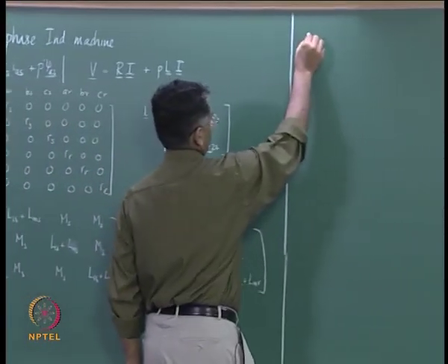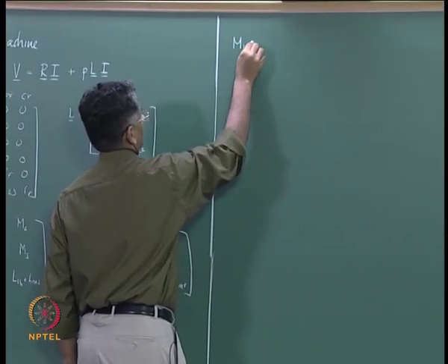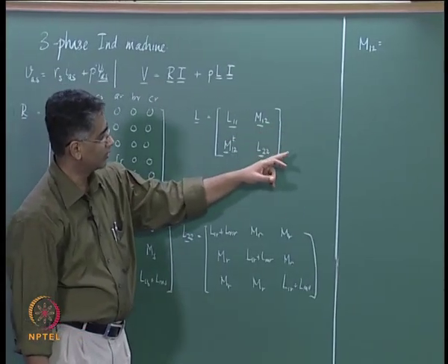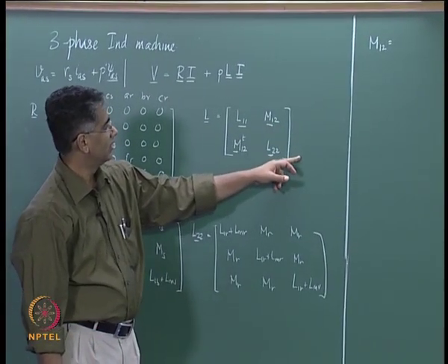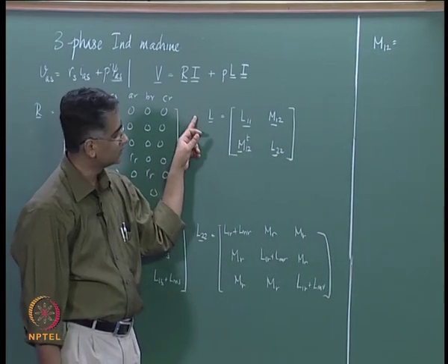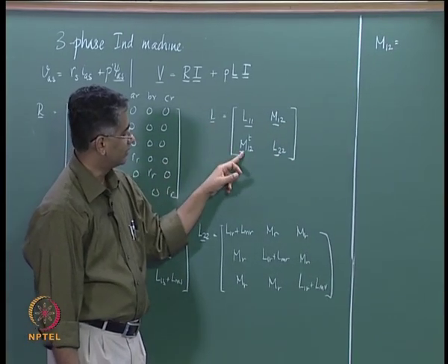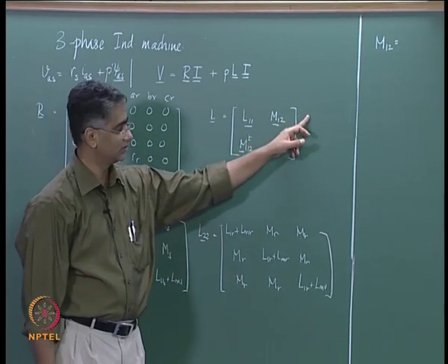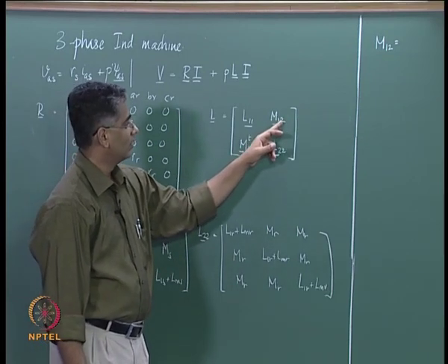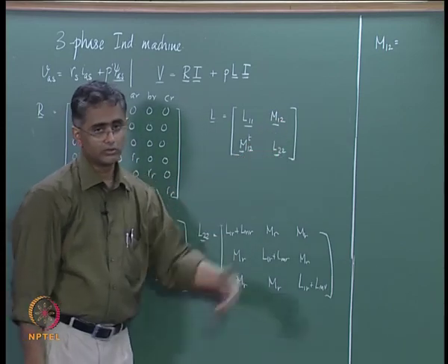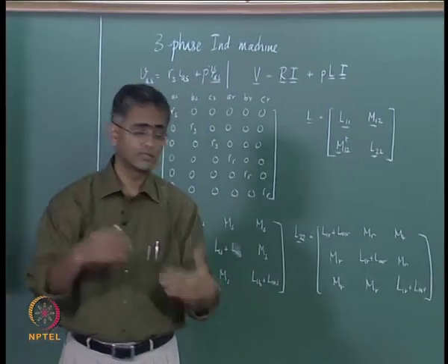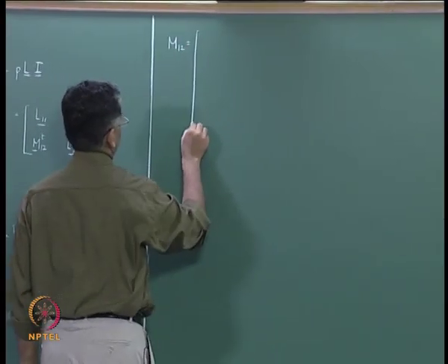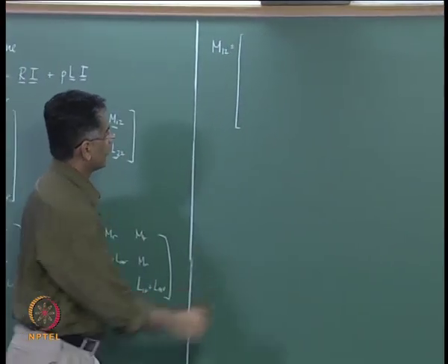M12 on the other hand describes the mutual flux linkage between the rotor currents and the stator flux. At this point it is between the rotor flux caused due to stator currents, and therefore M12 is going to describe mutual inductance behavior, and that we had seen the first row in the last class.